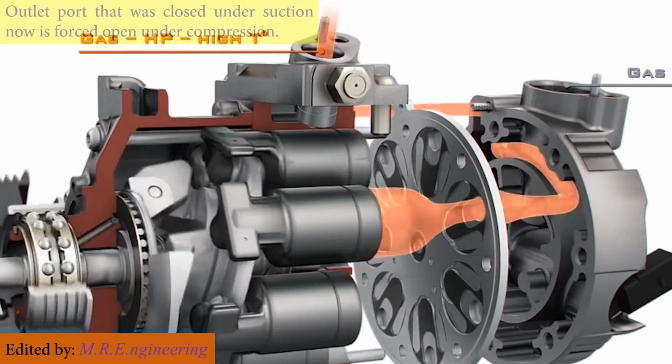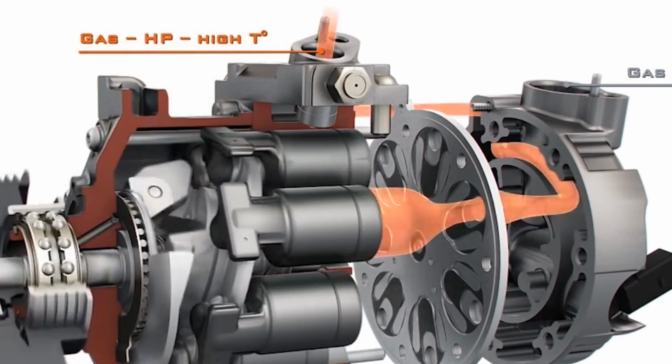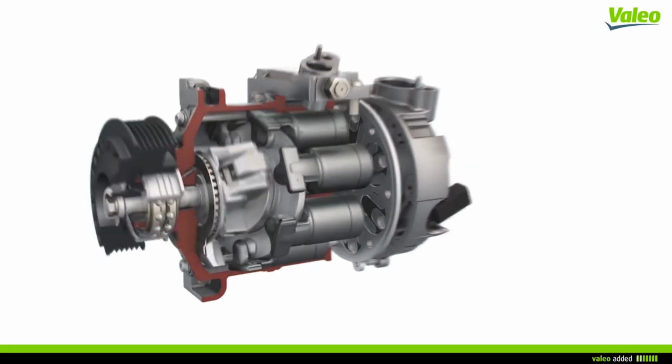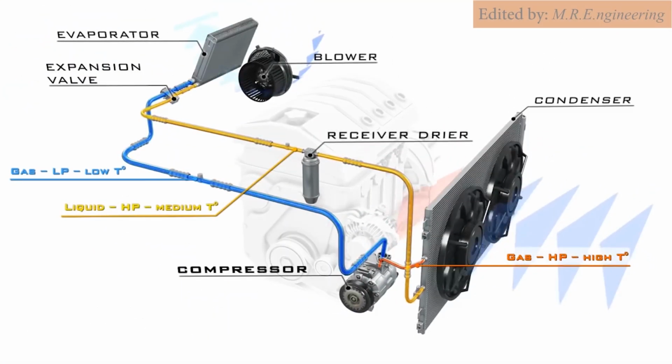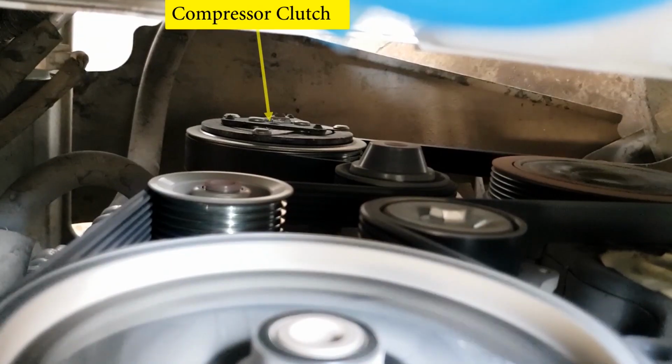This adjustment of pressure is accomplished by using a spring type steel plate for on and off type compressors that are known as fixed displacement compressors. To control switching of the on and off type compressors, there is a magnetic clutch that pulls and engages the rotating pulley with the input shaft of the compressor when you command the AC system to turn on, and some other requirements are satisfied that I talk about them in this video.